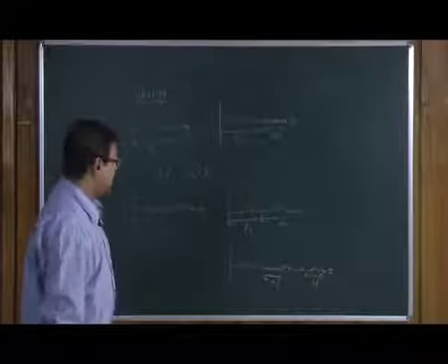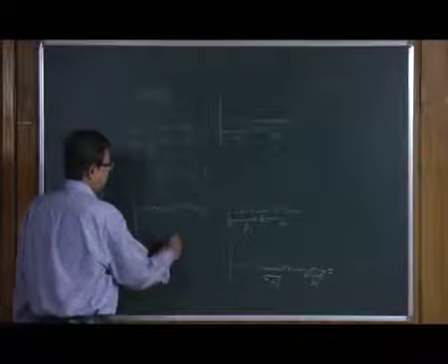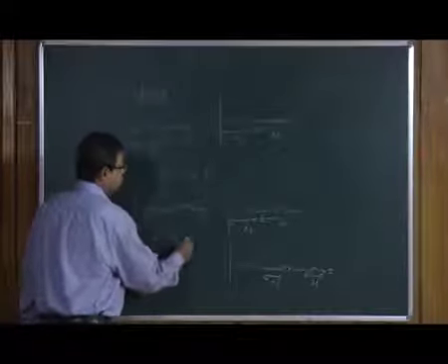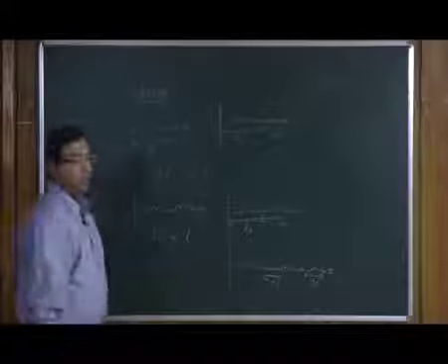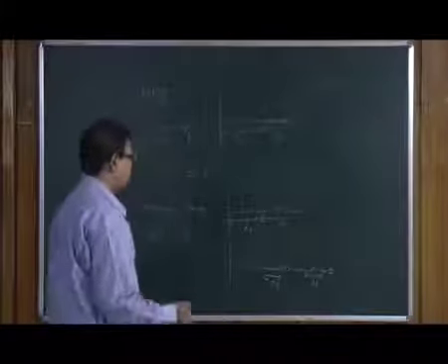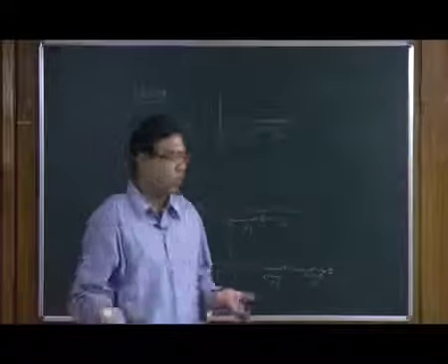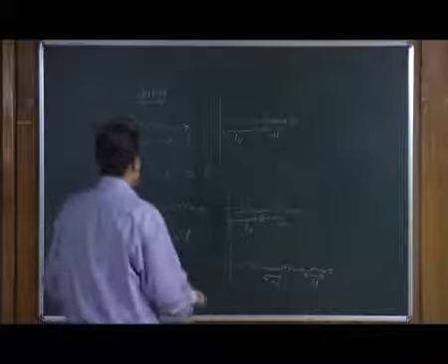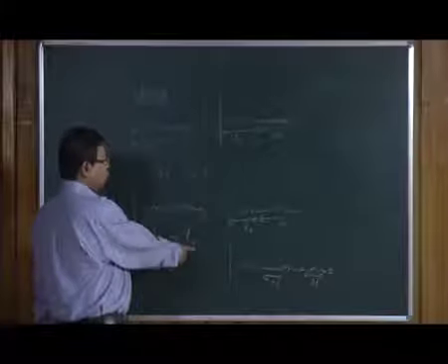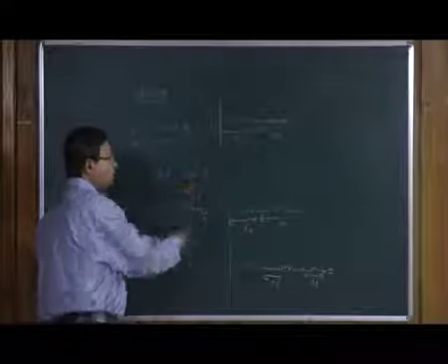So, which means that your delta L, the extension, is proportional to the original length L0. So, as we double the length of the spring under the application of the same force, the extension or the elongation becomes twice as much. So, delta L is proportional to L0, and we have also got delta L is proportional to F.